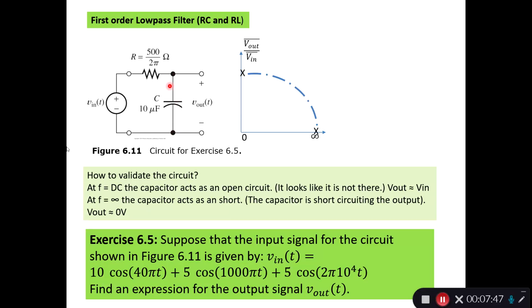There will flow no current through it, so I will just have Vin on this pin and on Vout as well. So Vout is equal to Vin. If my input signal is 1 volt, then I have 1 volt here too. So in this case, I get 1 volt over 1 volt. That gives 1 volt, so I'm up on the axis here.